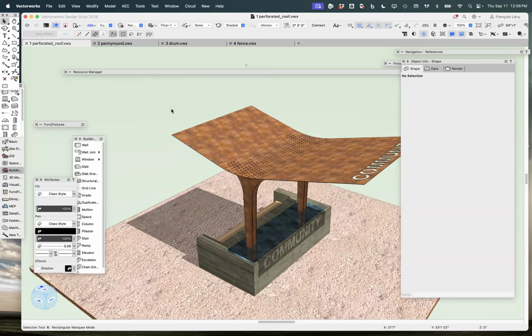And the one that I'm showing you on screen is probably one of the more exotic ones. I've got a meeting on site on Friday to meet with the builder. We're going to be doing this little entry pavilion. And here's an example of how I would use a surface array. So we're going to take a sheet of 8 foot by 14 feet, quarter-inch steel. We're going to laser, or I'm sorry, water jet cut it, and then we'll go ahead and roll it and then weld it to this structure.